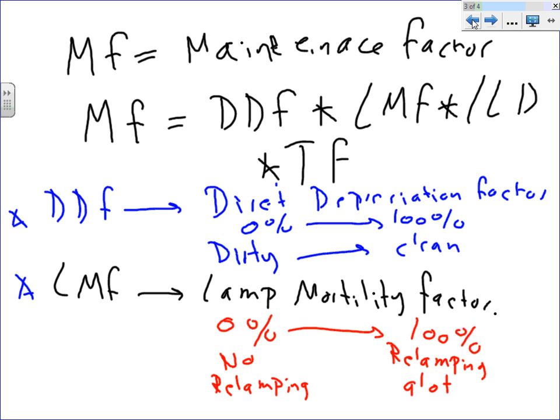Well, the quality went down. Why? Because of all these factors. The lamp is aging, so the lumen went down. Because it's dirty, they don't clean it. Because of multiple factors. So to cover ourselves as engineers and designers, we always take this into consideration day one, and we design the system, and then 6 months, a year from now, we're almost guaranteed that you'll be around 80. Here's the catch-22 though.